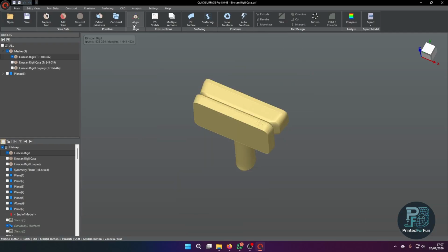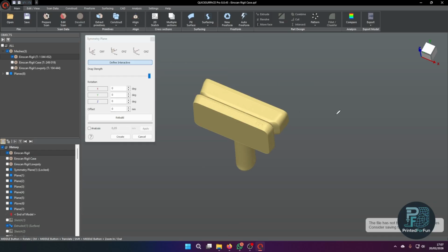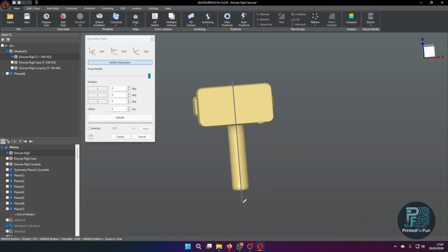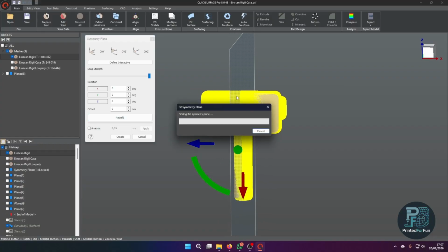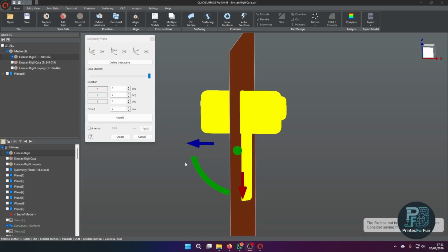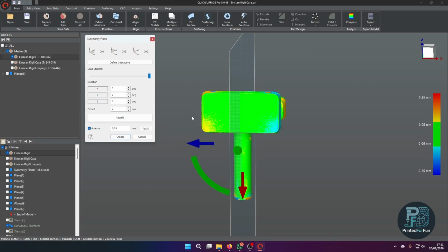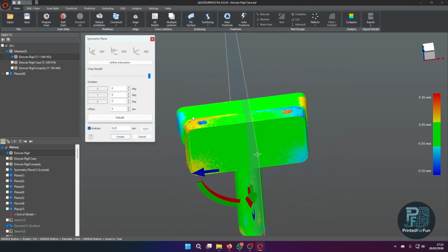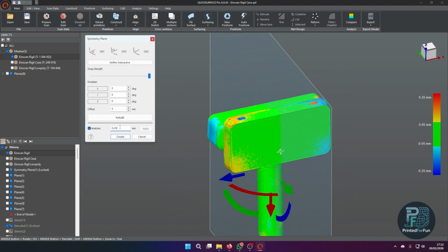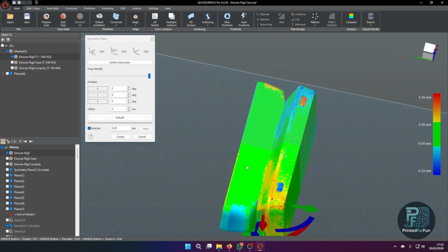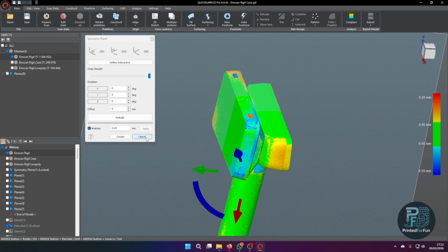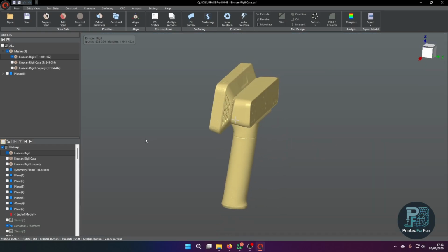it very much helps to refine the symmetry plane further. So you can see here, I can now manually rotate it and then the rebuilding process will be a bit faster. When creating symmetry planes, you can even have an analysis of how symmetric it is. So this is at 0.05 millimeters, and as you can see, the high spots are roughly 0.41 millimeter. For a TPU printed sleeve that will adjust a bit to the part, this is well within the accepted tolerance I like to have.